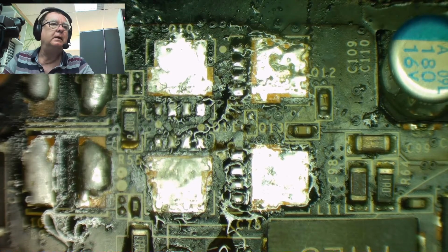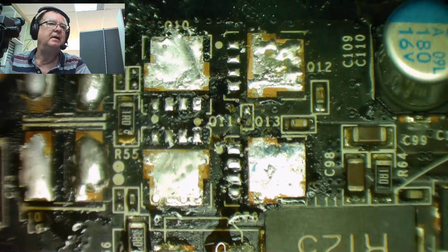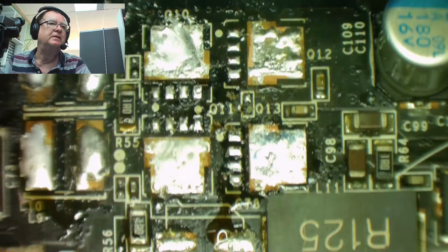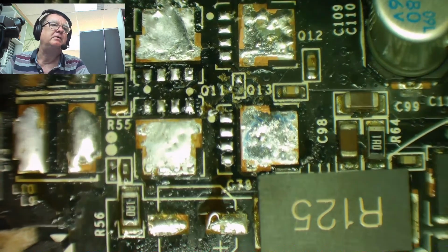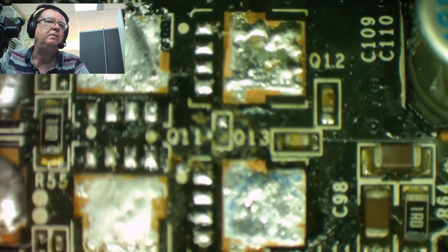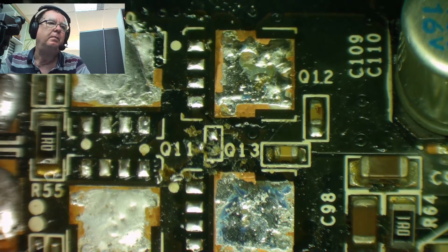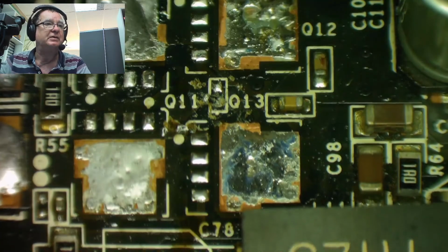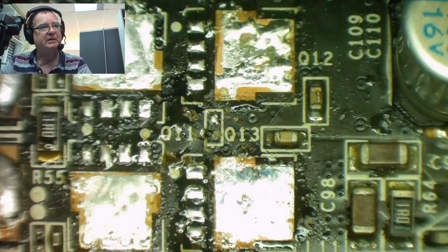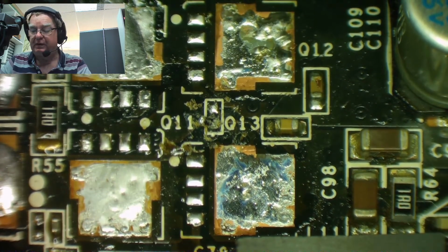Okay, so best thing with that, I think, is for me to go on to one of the forums, probably Bad Caps, and ask anybody if they know what that diode should be. I thought you said D. You know, that might be like a low value resistor. Hopefully, if we look on the example circuit and figure out where that is in circuit, that should tell us what that component is supposed to be. But I'll still ask first if anybody's got one of these and does they know what it is. If not, we'll get onto the data sheet, the example circuit, see if we can figure out what it is.